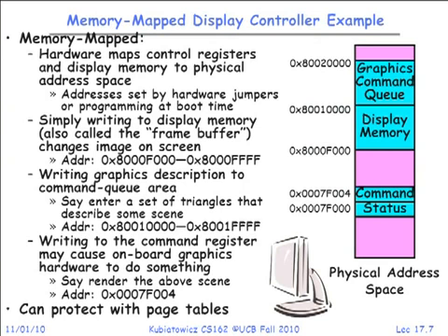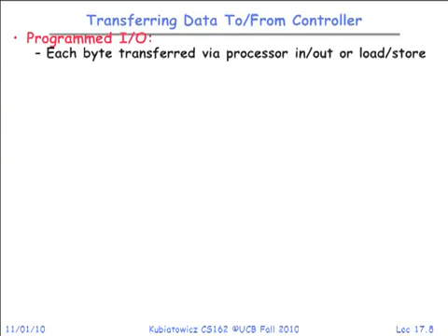Now, how do we get data to and from the device? What I've been telling you is a kind of primitive idea. I've got a load or a store, it goes to the device. What's a little bad about that is if I want to load a megabyte out of a device, does that mean I have to have a really tight loop with load, load, load, load? That sounds a little unfortunate, because it means I'm tying up processor time to do something so automatic it seems silly not to have the hardware help me with it. But that's what's called programmed I/O.